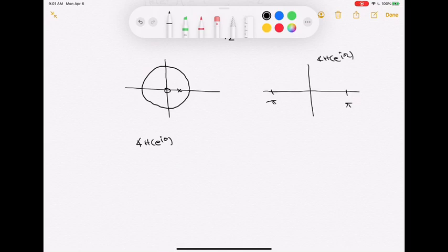In this particular case, we know that B0 was just a constant one that has an angle of 0 degrees. The next thing I'm going to do is add in the contribution from all zeros. I'm going to draw this in red. If I go from that first 0 to DC, it's just pointing straight off to the right. The angle that is making with the positive real axis is 0, so I'm going to get a plus 0 in here, something along those lines.